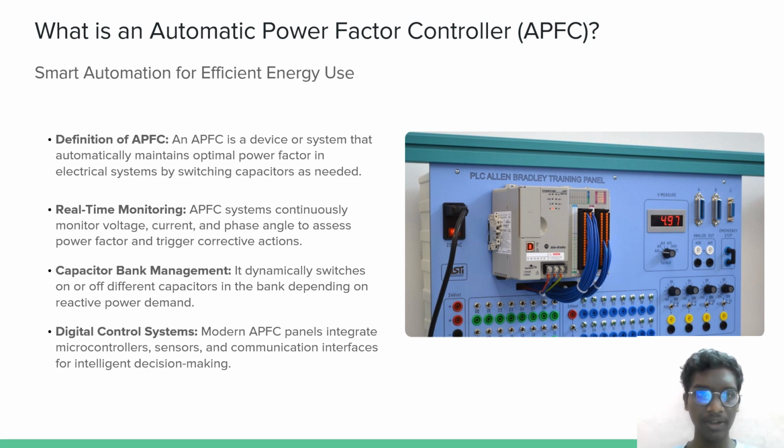Real-time monitoring. The APFC system continuously monitors voltage, current and phase angle to assess power factor and trigger corrective action. Capacitor bank management. It dynamically switches on or off different capacitors in the bank depending on reactive power demand. Digital control system. Modern APFC panels integrate microcontrollers, sensors, and communication interfaces for intelligent decision making.